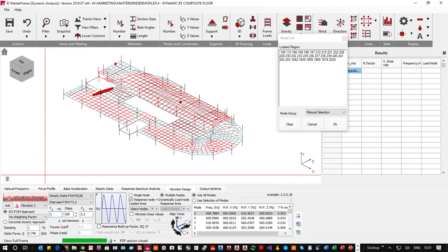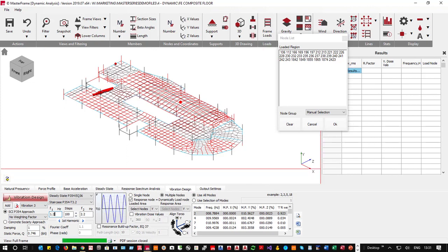change our values, and we're going to go for 1.2 all the way up. For a staircase, it's all the way up to 4.5. Now, 4.5 is one heck of a frequency, but if you can imagine two people running down the stairs, same weight, perfect timing, you could get up to double that normal value. We're going to run that all the way up on all the stairs. So let us go and see what we get from this.